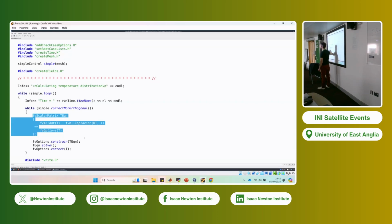If you want your solver to solve another equation too, you can simply add another line just like this one, provided that somewhere you define the variables. So what will be the name of your new variable, what will be the name of the new diffusion constant, but it's just as simple as that to solve new equations with OpenFOAM. You can simply create your own solver by adding lines to the existing ones.